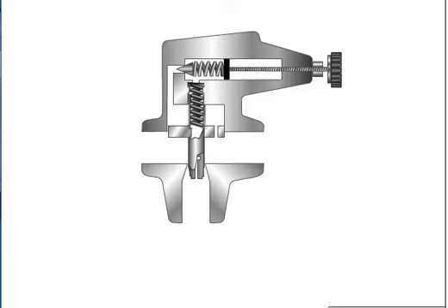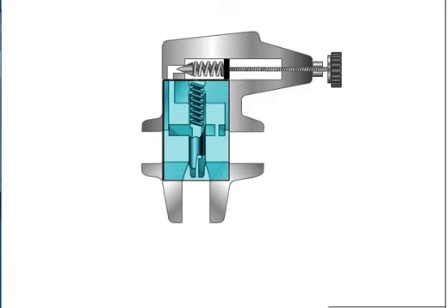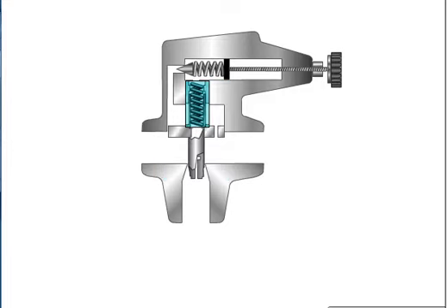The valve is built in 2 stages. The second stage includes the main spool, held in a normally closed position by a light, non-adjustable spring. The second stage is large enough to handle the maximum flow rating of the valve. The first stage is a small direct-acting relief valve, usually mounted as a crosshead on the main valve body, and includes a poppet, spring, and adjustable knob.